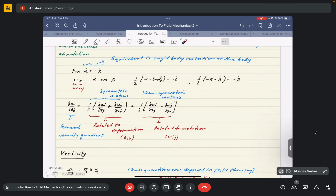Again, there is some more mathematical manipulation. That is, the velocity gradient can actually be written as a sum of a symmetric and a skew symmetric matrix. The symmetric matrix is essentially the rate of angular deformation matrix, and the skew symmetric matrix is the angular velocity tensor or angular velocity matrix.